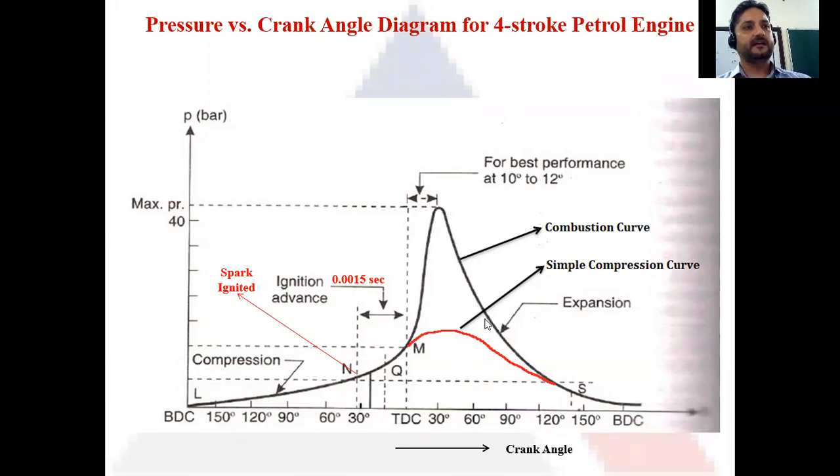These chemical reactions are producing some heat after the combustion has completed. That is why the graph is not going down steeply, but is reducing at a very gradual pace. This phase is known as afterburning, during which some energy or heat is being produced.